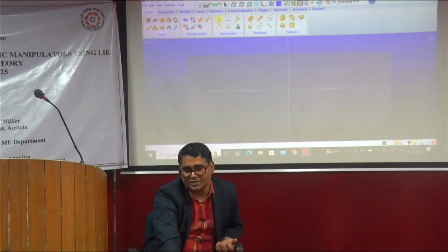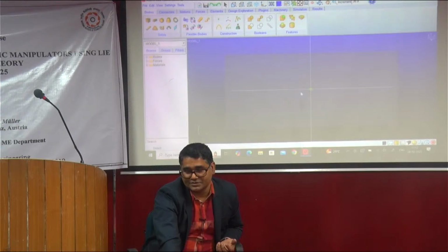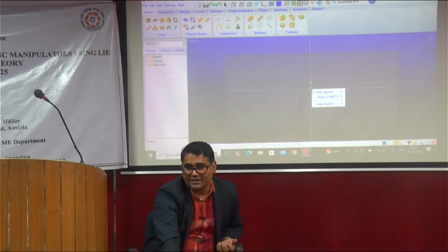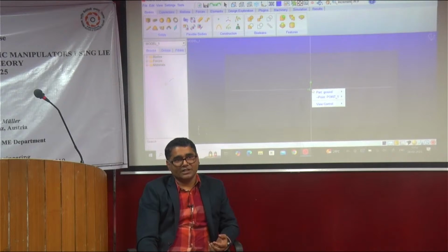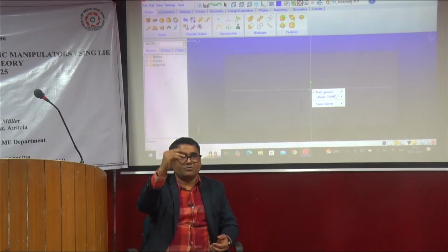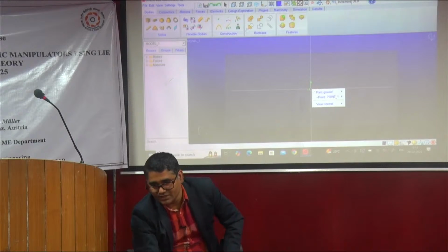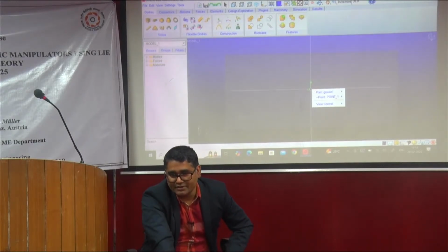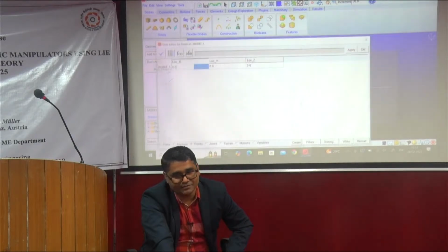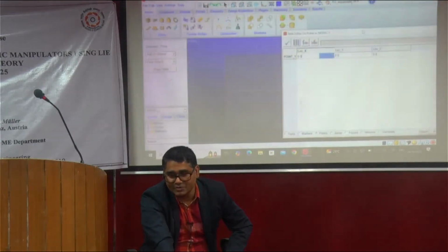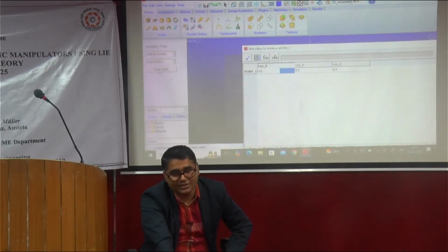I can simply click on the table point. Okay. And in this point, whenever you click, you will find different points. Okay. Now these points which we are connecting, we can make in the form of a table. Different coordinates we can give, x coordinate, y coordinate, z coordinate for that particular table. So how can we give that? Once you click it, you will get a point table. Okay. In this point table, you click it,